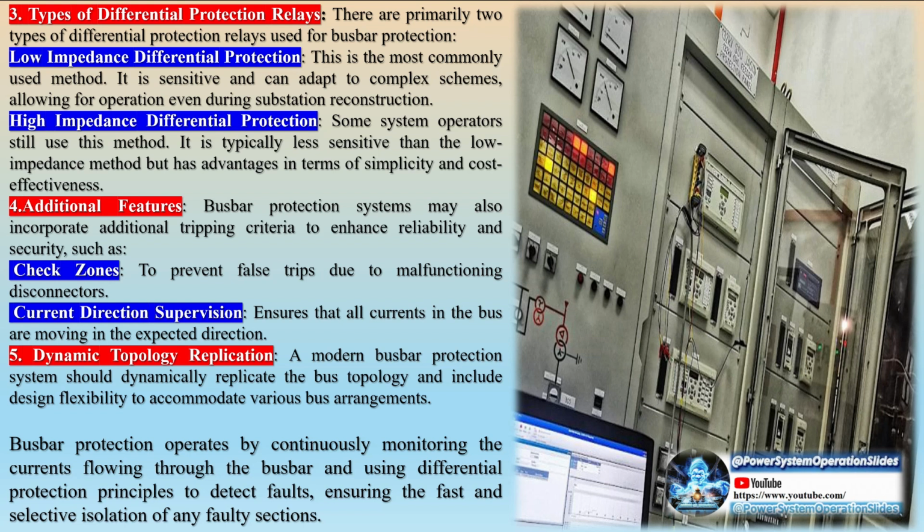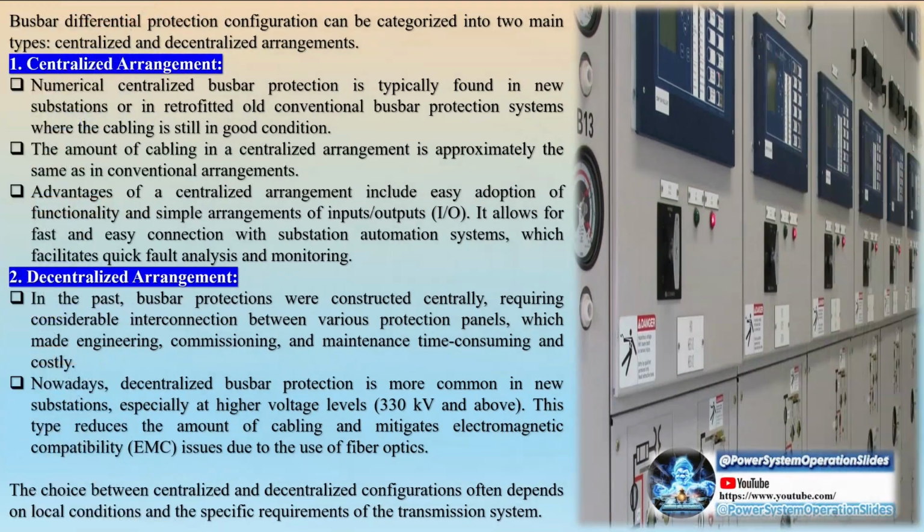Special busbar arrangements: components and their protection, and fault protection. Dead zone blind spot. A fault between a circuit breaker and a current transformer, and fault protection addresses faults in the bay between a circuit breaker and a current transformer, known as small zone faults. This protection is implemented for all bays except bus sections, couplers, and shunt equipment, covering the zone between the CT and the CB when the CB is open.